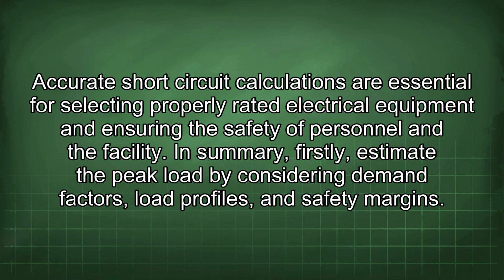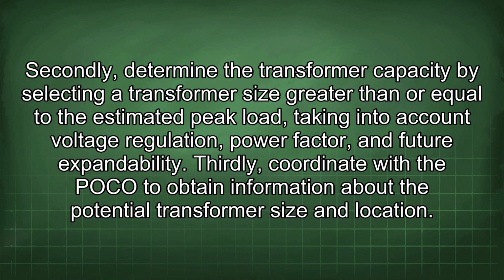In summary, firstly, estimate the peak load by considering demand factors, load profiles, and safety margins. Secondly, determine the transformer capacity by selecting a transformer size greater than or equal to the estimated peak load, taking into account voltage regulation, power factor, and future expandability.